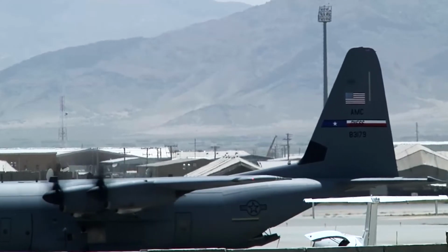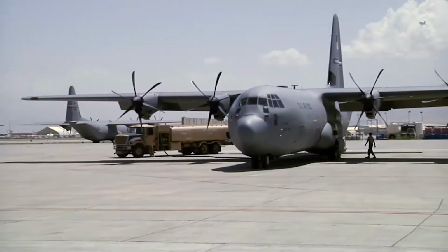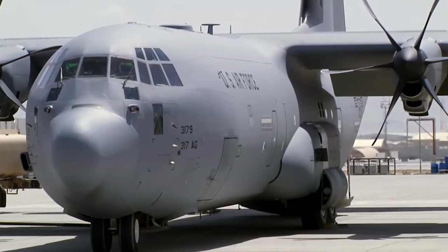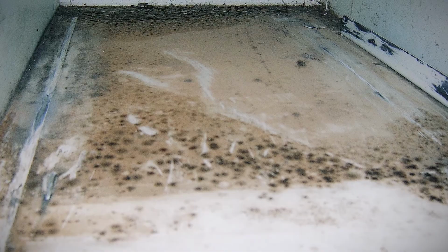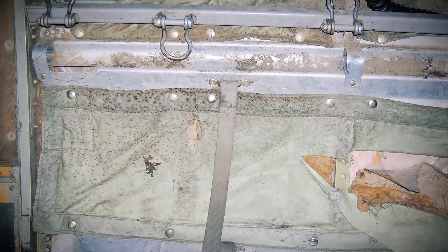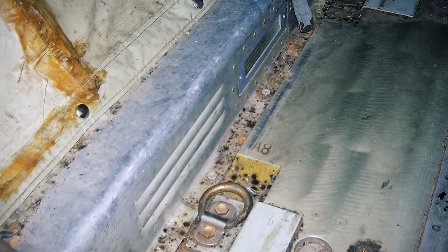High temperatures can cause serious corrosion of aircraft and support equipment. Hot temperatures accelerate corrosion initiation in vulnerable materials and also promote mold and bacterial growth. These small biological organisms that tend to grow in closed areas that remain damp for long periods of time can induce corrosion that remains undetected.